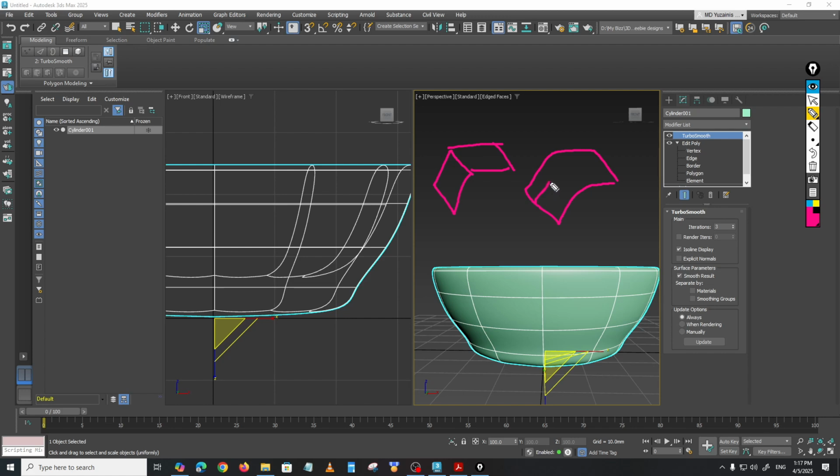So now it becomes like 4 here, and then there's also this, so it becomes multiplied. The higher the number, the more it multiplies, and the smoother it's going to get. This is how it works. The low polygon angle of the faces helps to guide the direction of the curvature of the high polygon model in the Turbo Smooth.